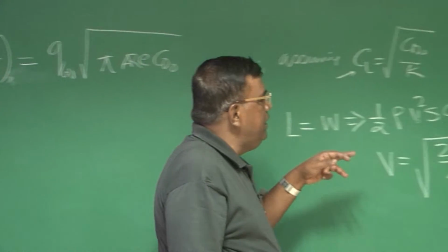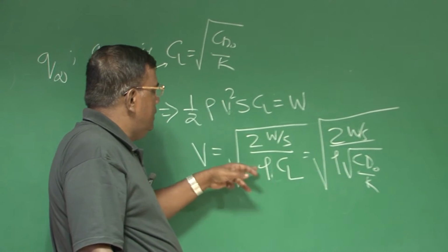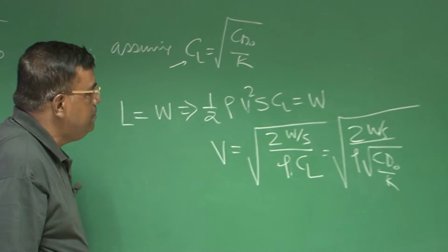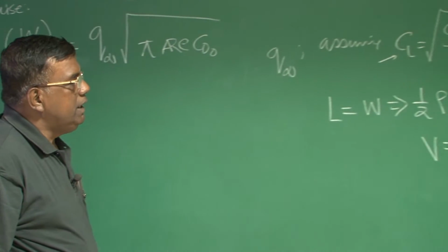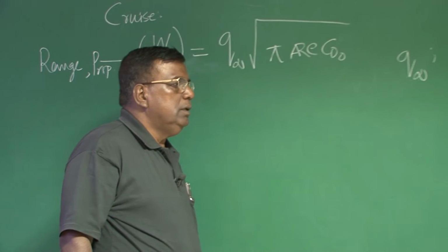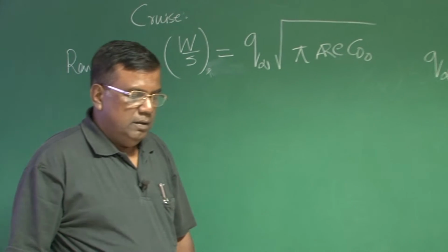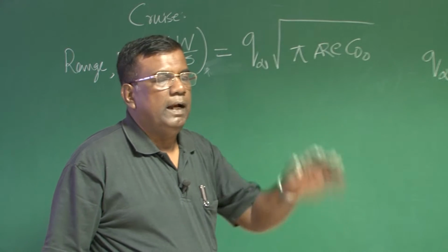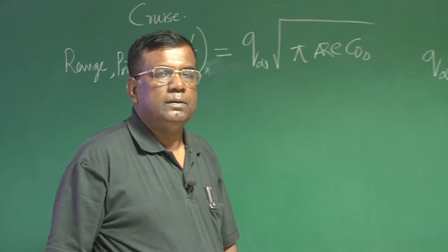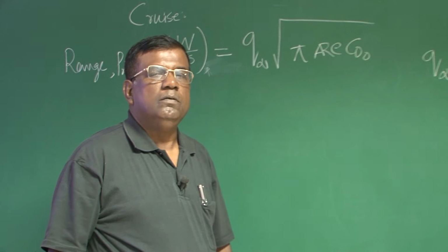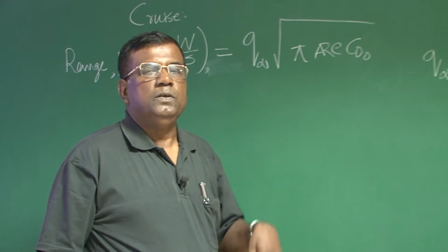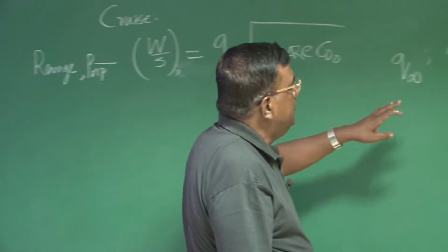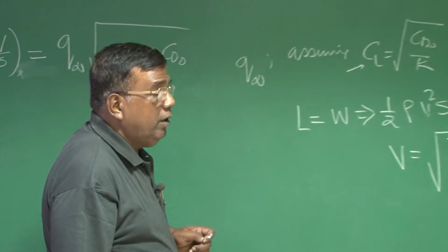Theoretically, you can have that pre-specified V by flying at different altitude, rho, but the practical limitation is these altitudes are fixed by designers when they tell, please fly at this altitude where engine will be most efficient, or an air traffic controller will tell, this is the altitude available for you. So this sort of a conflict or decision making point comes.